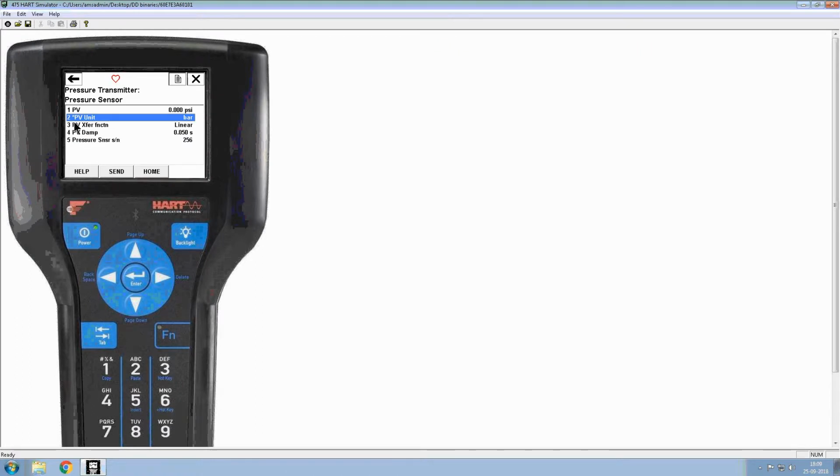Notice an added asterisk just before the parameter. This indicates that there is data to be sent to the field device. You need to click on the send button provided here to actually send the appropriate command that writes the new data on the field device. Click on yes when prompted for ignoring the next 50 occurrences of the modification change status bit. This sends the data to the device and removes the asterisk from the parameter. Let us put it back to the default PSI unit.